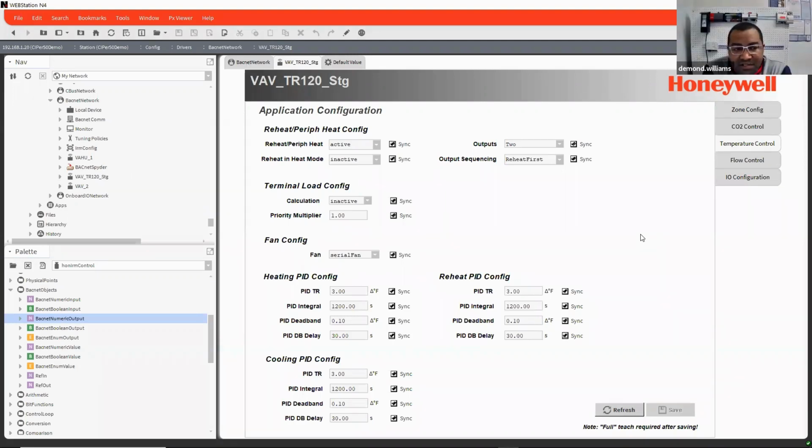Yeah, no, unfortunately, any modifications, once you got those Silk devices on there, that's the only thing. And I've reported that to Honeywell to see if they can work on that. But anything dealing with the Silk devices, if you make any changes or even move the function blocks, it's going to force you to do the full teach again. It's just the way they're doing the Silk devices, it makes it look like it's been a major change, and they force you to do the full teach again.